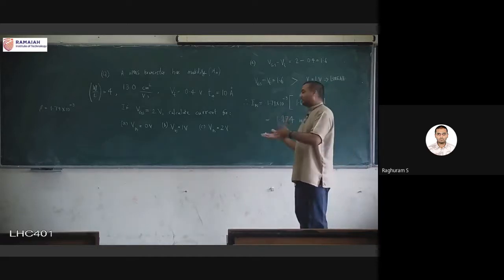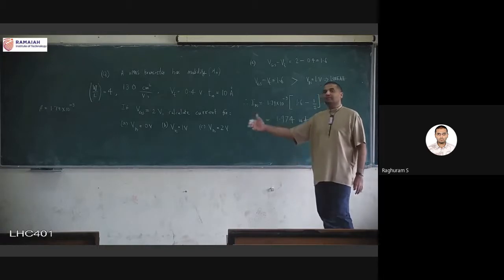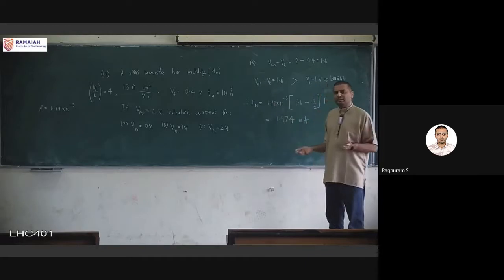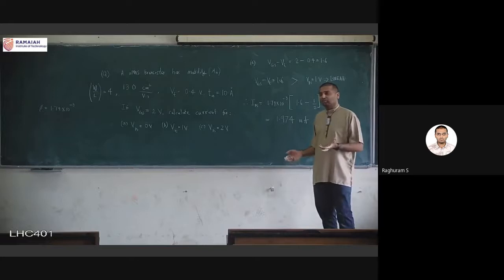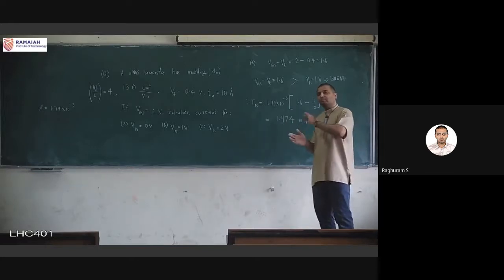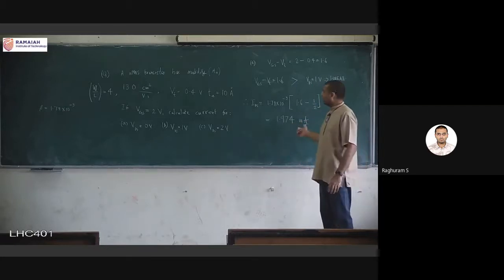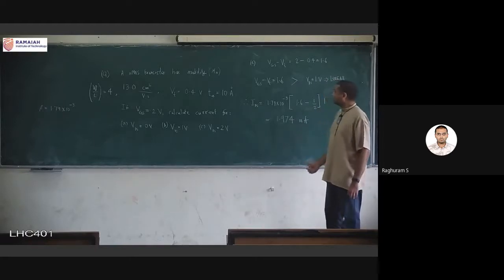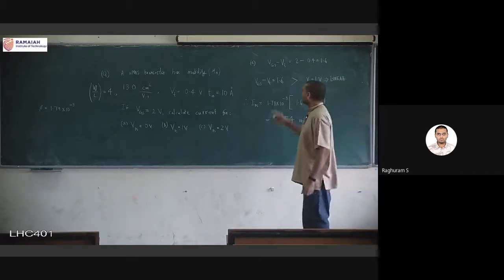And in the other direction, suppose instead of 1.974 milliampere you go to microampere. Maybe 100 microampere you might get in some situation, but 1 microampere is a very small current also. So hopefully we stay in the range of milliampere to microampere. Anything below 1 microampere you have to recheck the calculation. That is why the numbers that we get for the current are also important. So this is the first case, 1.97 looks okay, so we can move on to the next case.